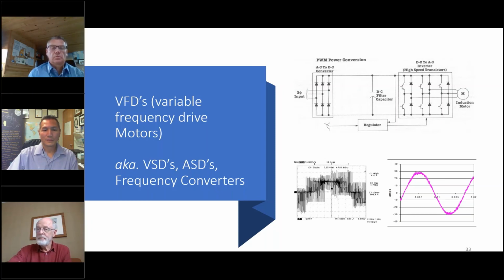Karl, Shreyas here from India. Just to add on to that, the query was because of the PDIVs that the motor needs to be designed for. So I had a query on what would be the typical dV/dt value in the industry, whether it is 10 kV per microsecond, or just an example of how you've seen for a 50-meter cable length.